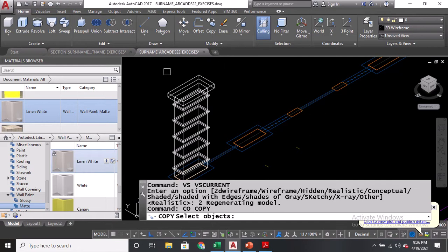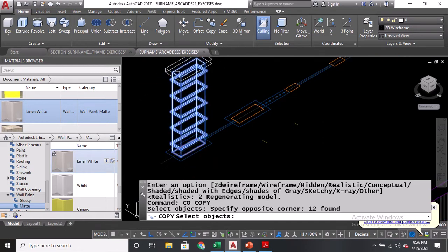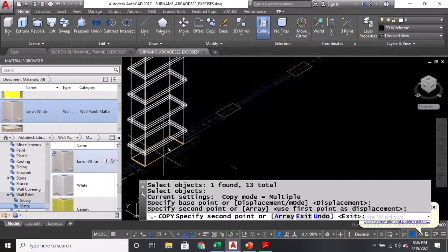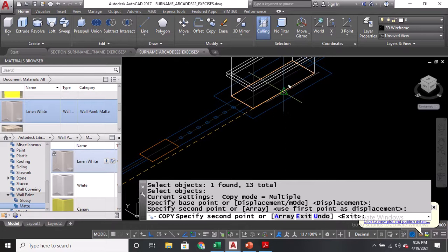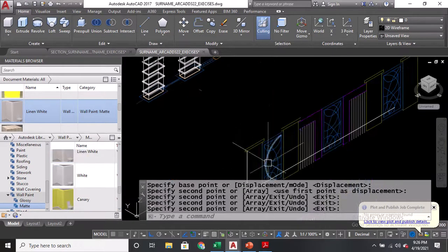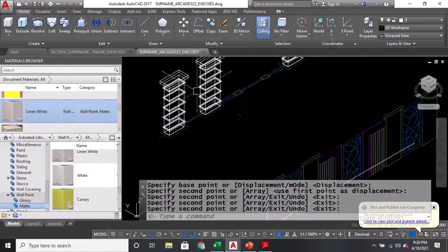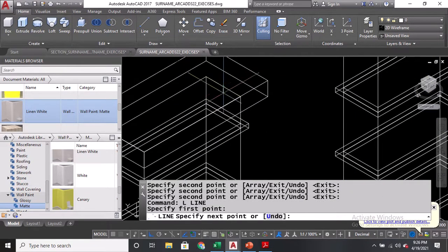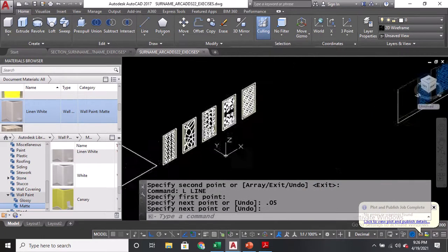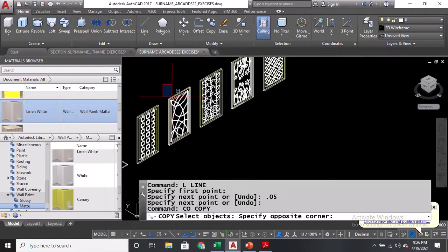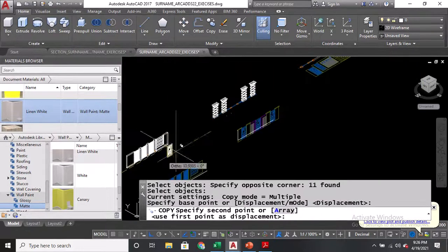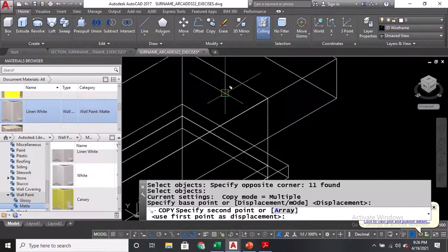Copy. So, let's select this object. And I'm going to click sa midpoint. 1, 2, and 3. There you go. And followed by this 3D metal plate. Again, I'm going to type L. That's 0.05. That will be my reference for copying. And then, eto na siya. So, CO. Enter. So, I'll be picking the midpoint. Lagay ko siya dito. Okay.